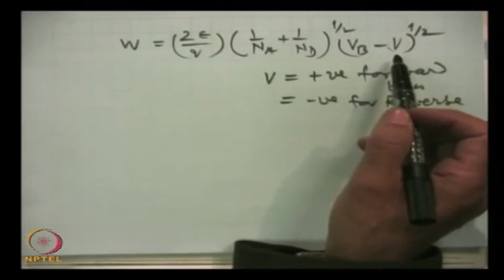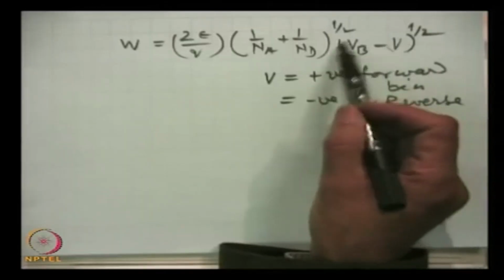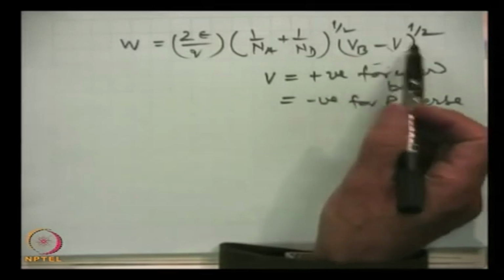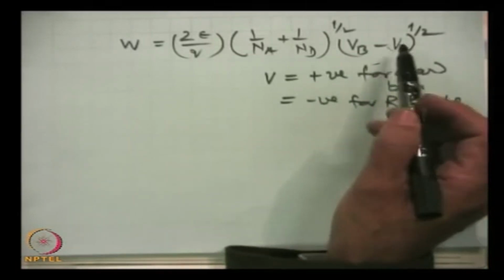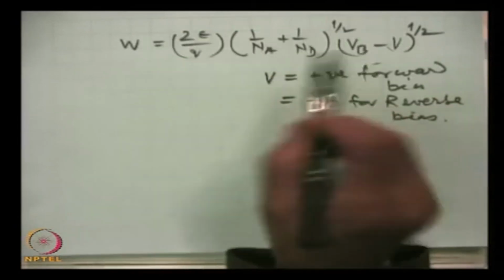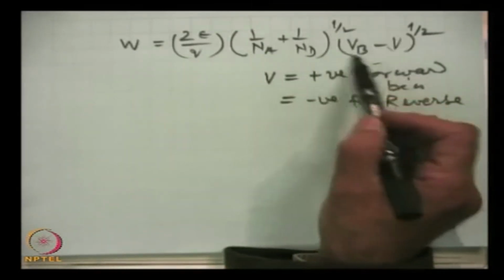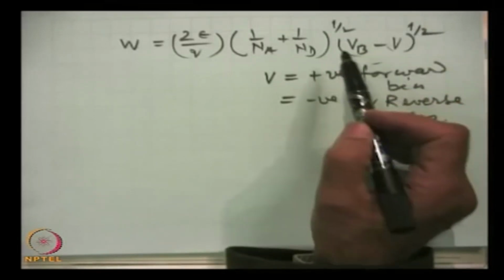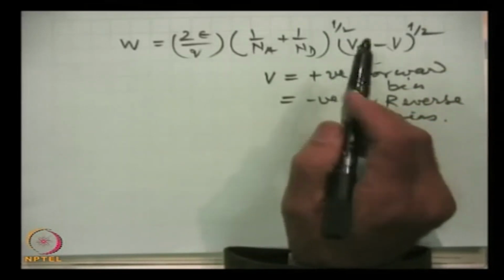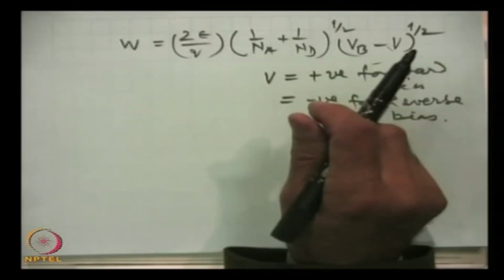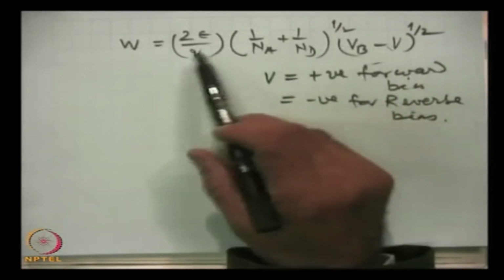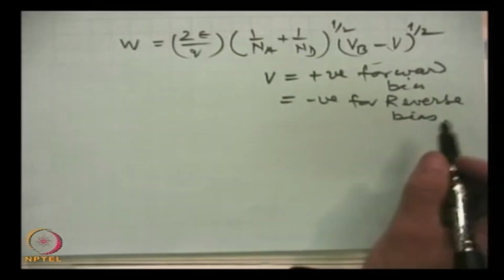At the moment we are discussing the forward bias, for that it is positive. So, the depletion width will decrease, but one point to be noted is that this term will never be negative, because when we increase the voltage, the current becomes higher and higher, making this term never 0 or never negative. Depletion width will tend to be 0, but it will not be 0, and it decreases with the forward bias.